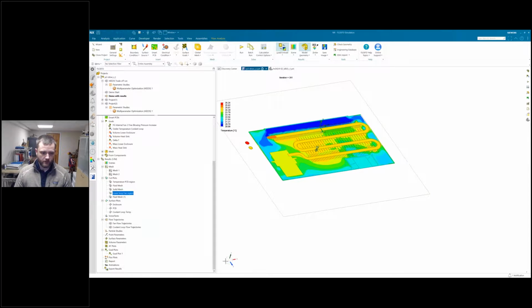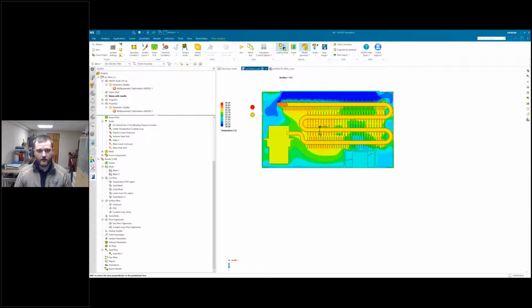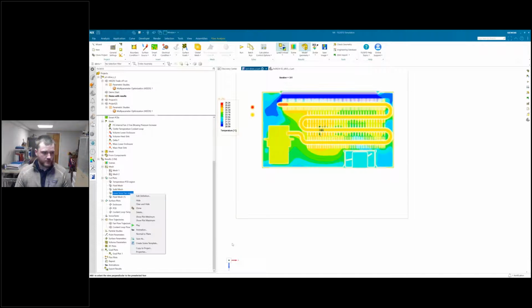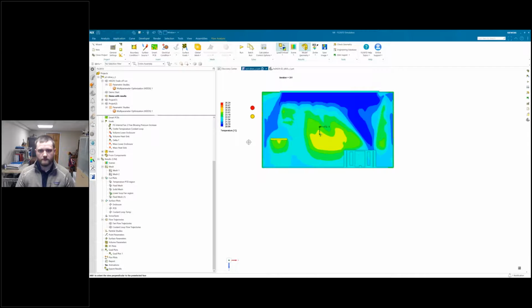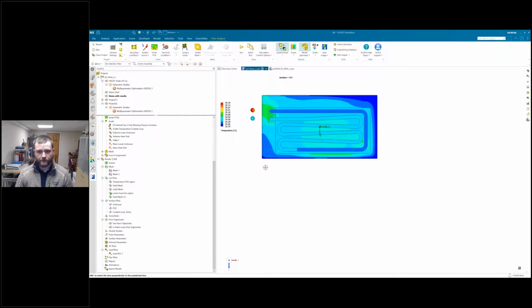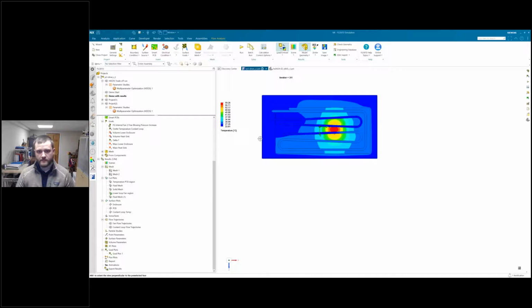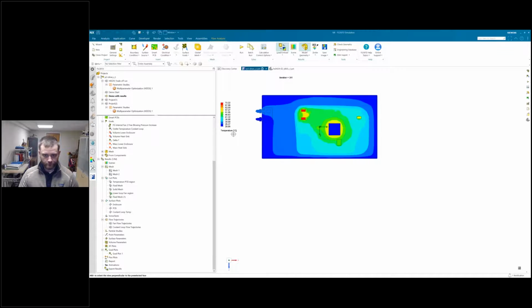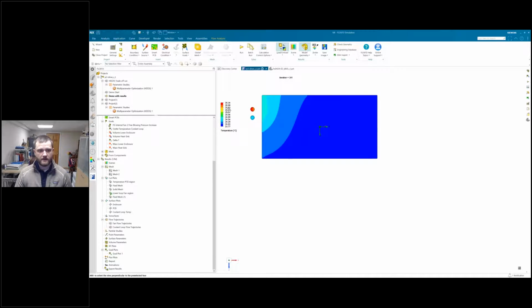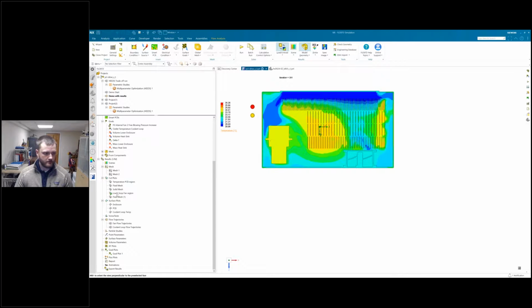And we're just doing a quick cross section here, this goes right through the radiator and the fluid pipe within that radiator, as well as the fan and the pump. And we can animate this really quickly just to show the overall temperature change through the entire system. It's just going to sweep up and down through. So our PCB shows everything. And we can easily change these values if we want to look at the velocity just by stopping this.